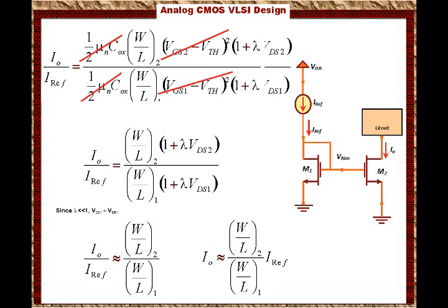This is a very practical circuit we have to learn, and a very useful circuit that we actually use when we develop analog IC circuits. Very fundamental, but it is used. Why do we have to learn the circuit? Well, when we implement the current source, we said that we implement it using a resistor, and this resistor takes a large area.